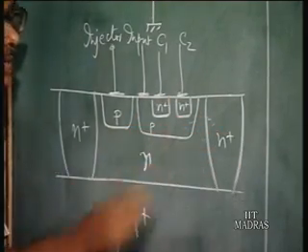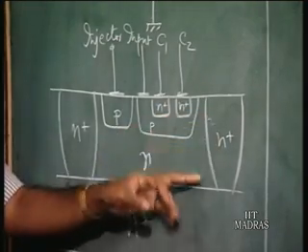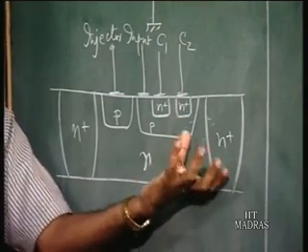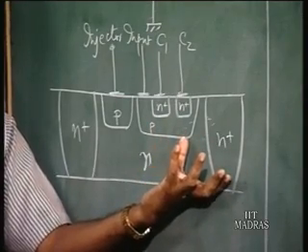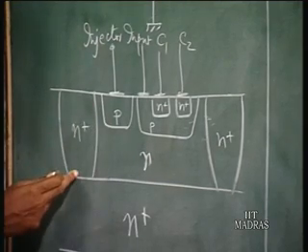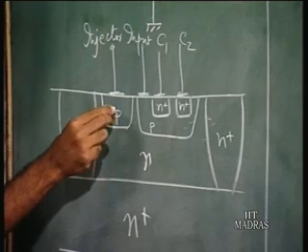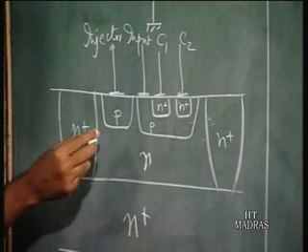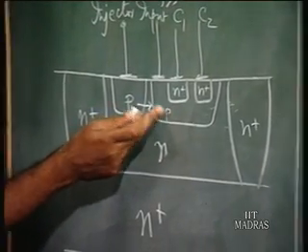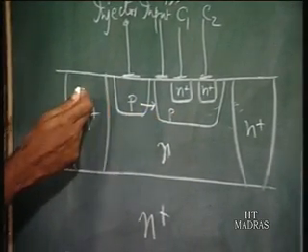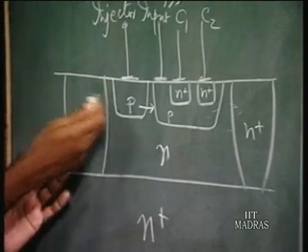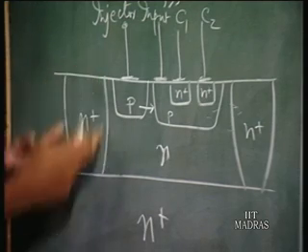So, basically it is for this reason you would like to have a guard ring, because any unnecessary n region left here is going to have some stored charge, which is going to create problems. And why a guard ring on this side also? Because again, if you look at this PNP transistor, the useful holes are those which are injected from the emitter towards the collector. We do not want holes injected this side, because they are not going to be of any use. So again, to reduce this injection of holes on the other side, you can make an N plus,